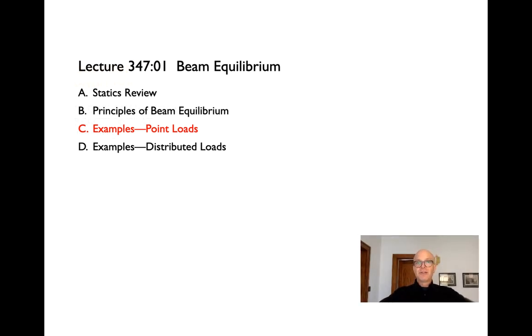We'll look at sort of flipping the seesaw over, where the loads become the support, and the support becomes the load. And in the next video, we'll do some examples that show how that seesaw principle, along with what we need to know about the conditions of the supports, can help us actually, through a little thought exercise, figure out what the reactions have to be on a given load with a point load on it.